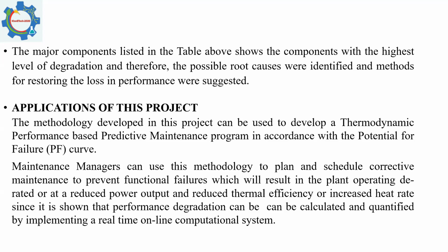A couple things just to note also, as I said previously, in relation to these design performance parameters, manufacturers do not normally provide those things. They are not available in terms of, for instance, the design isentropic efficiency of the compressor on the gas turbine. That is well known. It really runs between 85 to 89%. But the exact specific value is not provided by manufacturers.